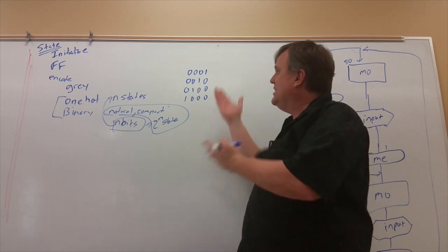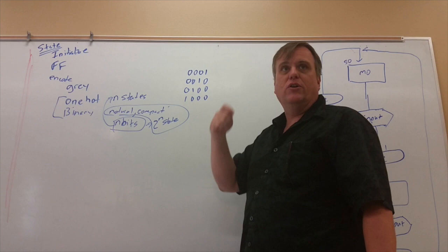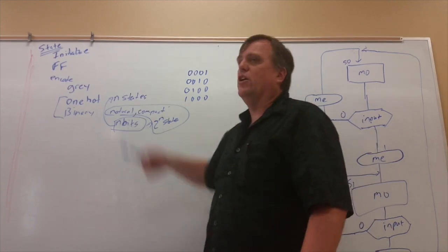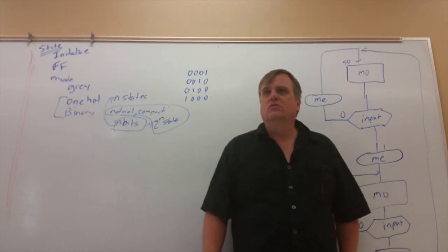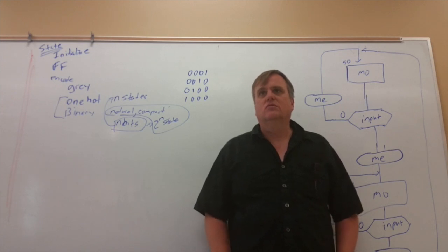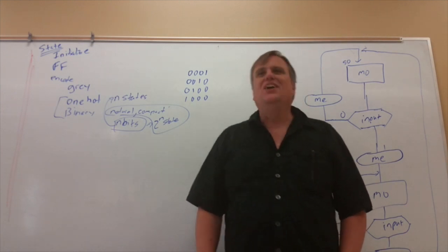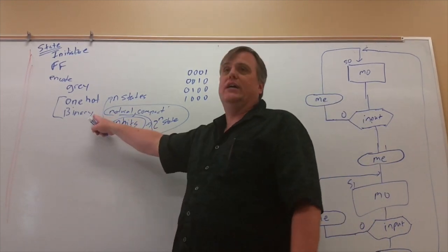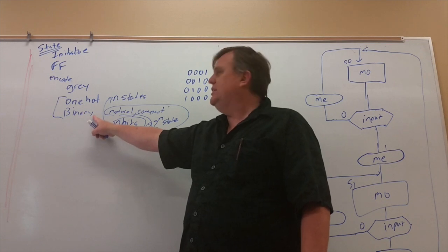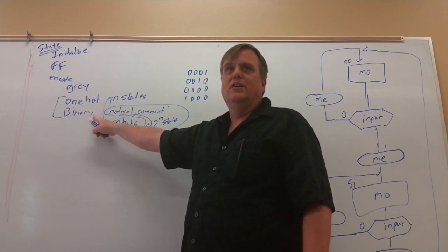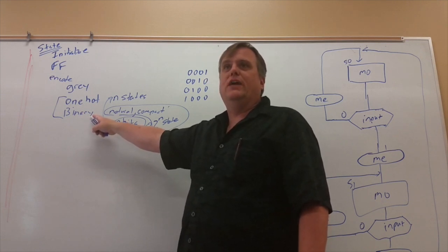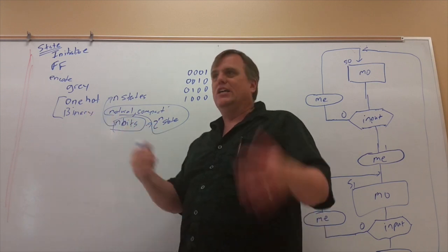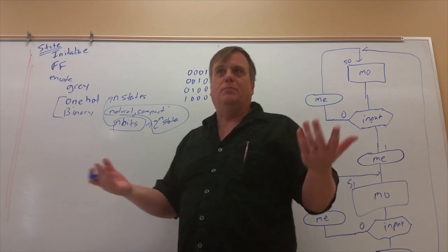Again, space inefficient, time very efficient. What's gray code used for? Is gray code the one where there's only one change between two? Exactly. Between 2 consecutive numbers, only 1 bit flips. It's highly compressed, so it's got the advantages and disadvantages of binary. And it has the added lovely advantage of almost nobody can read it. Right? Because they confuse it, because it looks just like binary and people misread it.